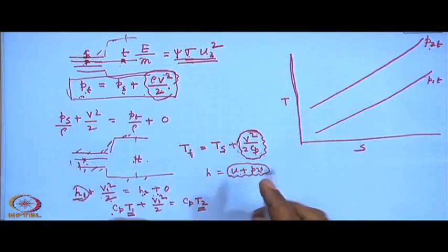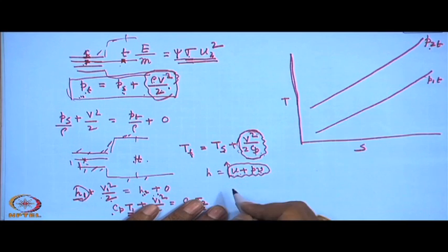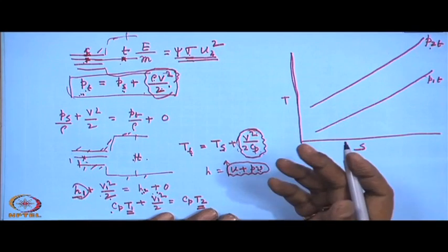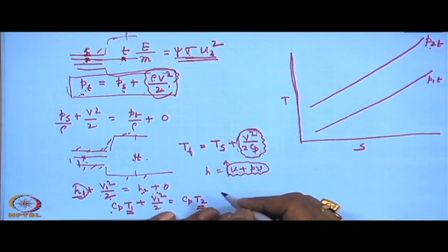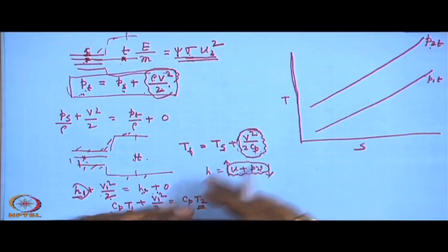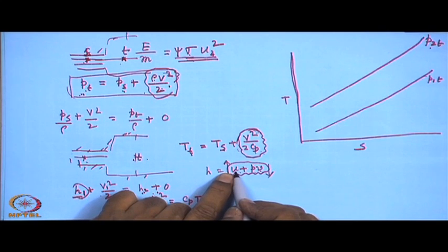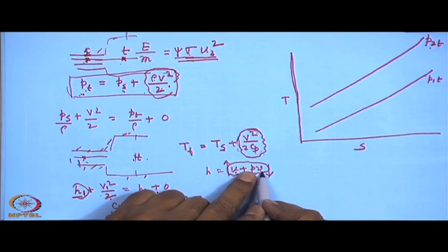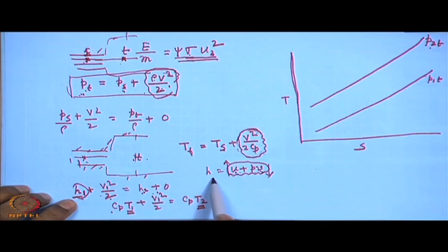They will adjust. If friction is there, U will be more, the internal energy will be more because of the friction, whereas PV is less. The reverse is there if there is no friction: U will not change, because the internal molecular energy will remain the same because of the temperature, and PV will take up the change in H.